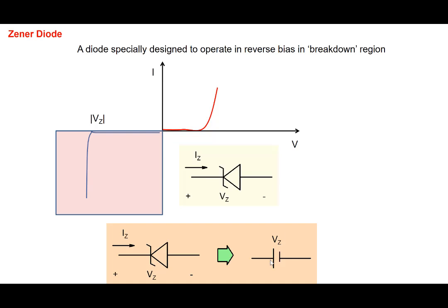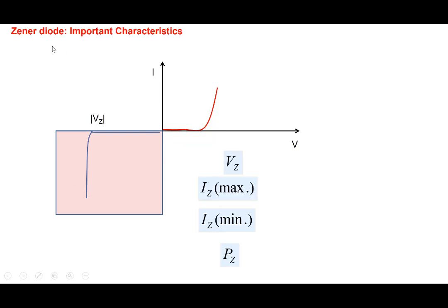and obtaining a very good value of output DC voltage here. So we can take advantage of the Zener diode. And when we are using a Zener diode, of course the Zener voltage is important, but we also said that there is a maximum Zener current and a minimum Zener current. Every semiconductor device, every resistor, every diode, every transistor has a maximum current rating, and if you exceed that, then the device may get damaged or not behave in the expected manner.